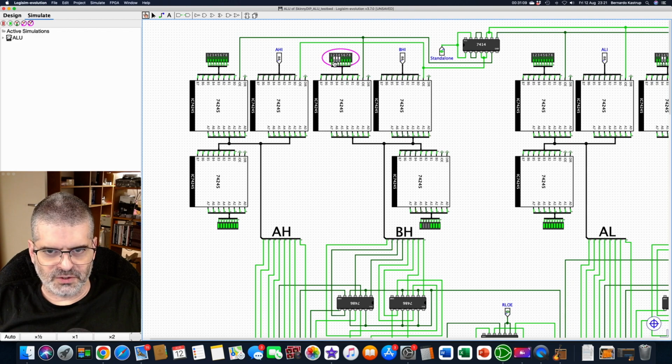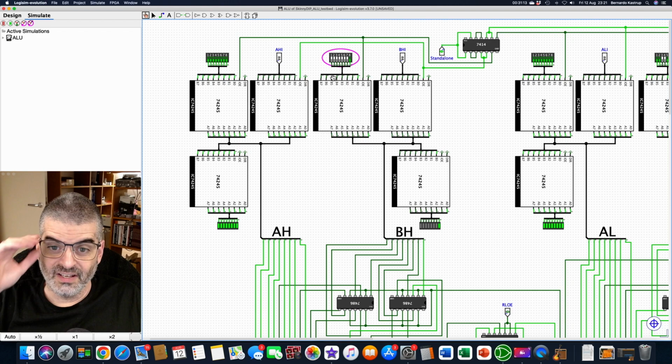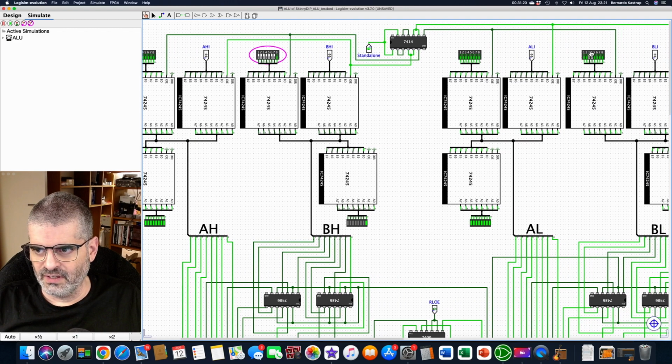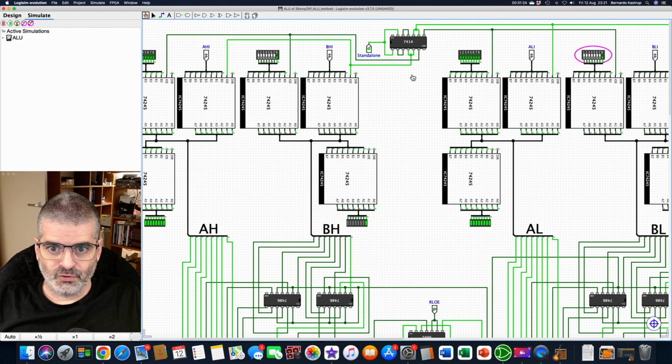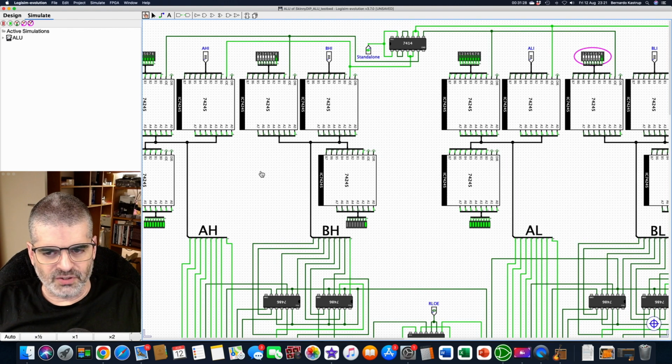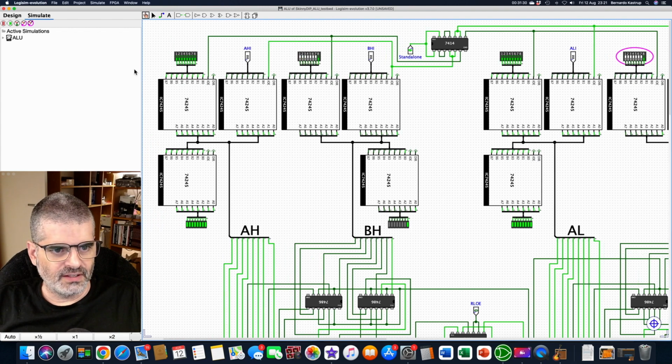It doesn't matter what we add now. Let's add only 1, so it would have to be 256. So it will be all zeros, and the carry flag will be high. That's what we should have: 0, 0, 0, 0, 0. So I'm trying to add 1 to 255, which should be 0 with both carry flags visible or active.